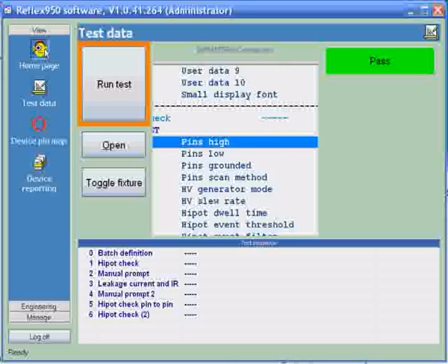One of the options we have in the system is a binary algorithm pin-to-pin test, and what that does is to ensure that every possible pin of a group that you specify has had the electrical test performed on it in such a way that there's been a complete polarity reversal between it and any of its neighbours. So in the case of this 155 pin test, it makes a complete test in only 7 routes.